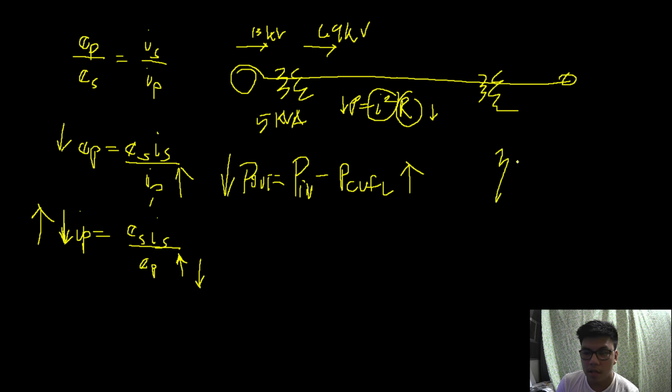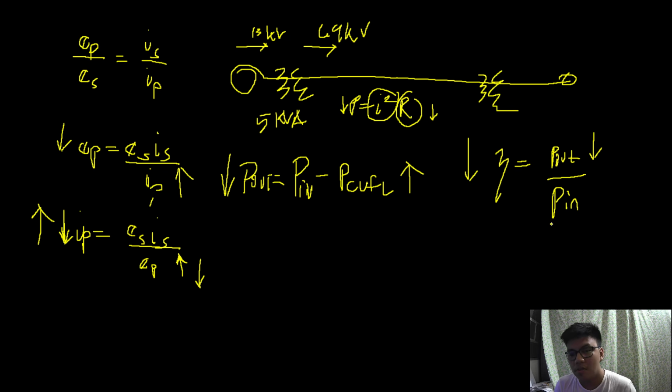So, alam natin na efficiency, that is the power output over power input. Okay? So, habang bumababa ang iyong output, bumababa rin ang efficiency mo. Okay, yung usable energy or power, nababawasan. So, that is one of the reasons why we step up or step down voltage. Okay, so for efficiency ng ating power system. Okay, so any conductor na daanan ng kuryente ay nagdi-dissipate ng energy. So yun nga yung power loss. So ang aim natin, mabawasan yung power loss. I-step up natin yung voltage, bababa yung kuryente, bababa yung power loss. Okay, so sana malinaw sa atin yung part na yan. And yun lang. Okay.